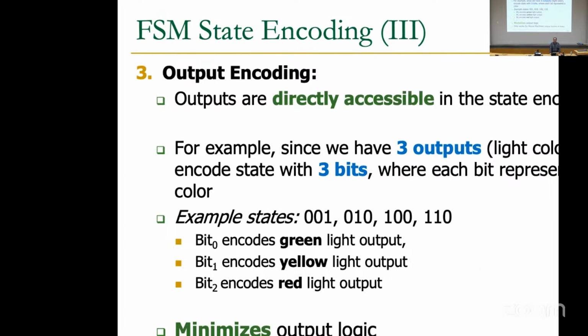Why is it the case? Why can't we use it for Mealy machines? Because in a Mealy machine, the output is also dependent on the external input, and you don't know about it, right? So you cannot encode the output using your states only.